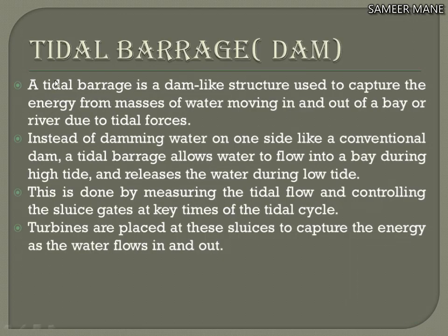Let's see the tidal barrage. A tidal barrage is a dam-like structure used to capture the energy from masses of water moving in and out of the bay due to the tidal forces. Instead of damming water on one side like a conventional dam, a tidal barrage allows water to flow into a bay during high tide condition and release the water during the low tide condition.